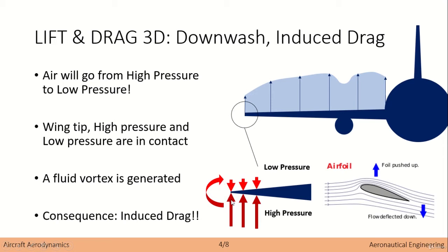So the vortex, okay, some kind of fluid vortex will be created due to the fact that we have in one point different pressures, okay? So there will be some kind of movement of the fluid around the wingtip, which we must avoid, okay? We must avoid this because it basically generates induced drag. An induced drag is just an additional drag which makes the vehicle less optimal,